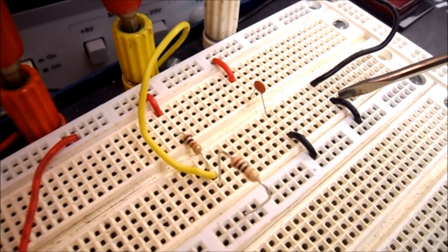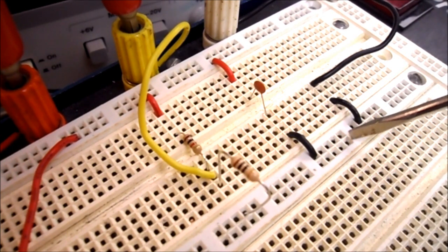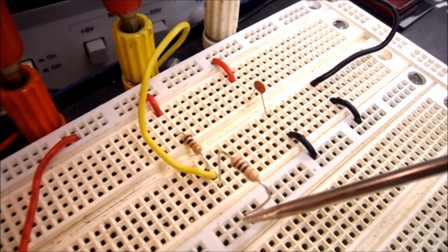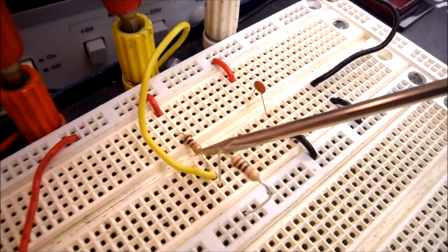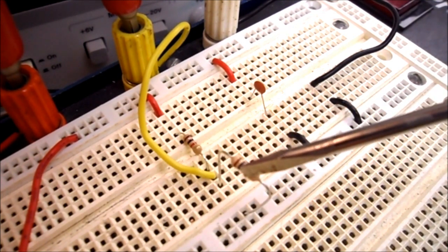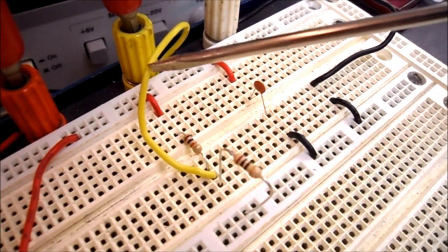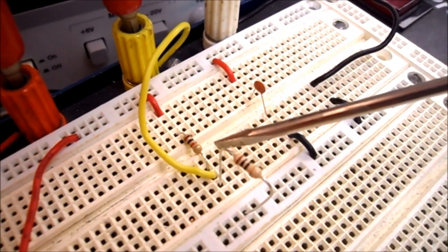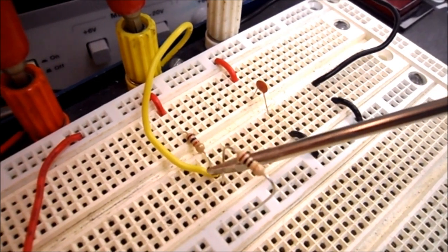So I've removed the 10 ohm resistor from IT, and I've replaced it with a little black wire link. So that now connects the entire bus line down here to ground. And I've taken out the little link that I had into the 1K ohm resistor and replaced it with a 10 ohm resistor. And you can now see I have the wire coming from channel 2 of my oscilloscope to the midpoint of the 10 ohm resistor and the 1K ohm resistor.